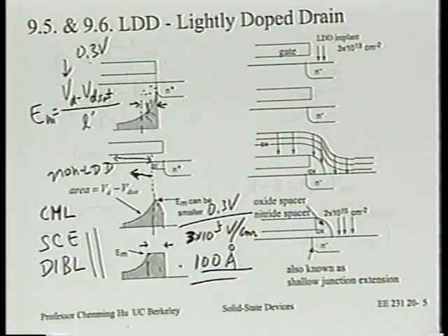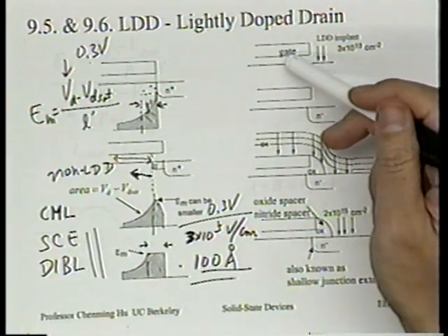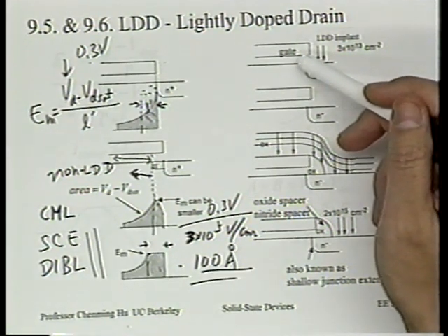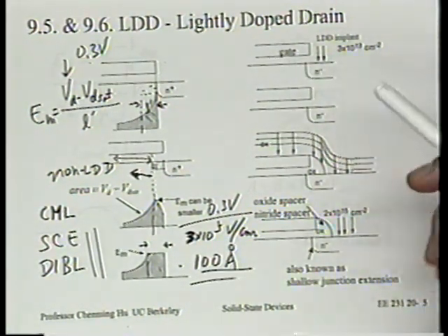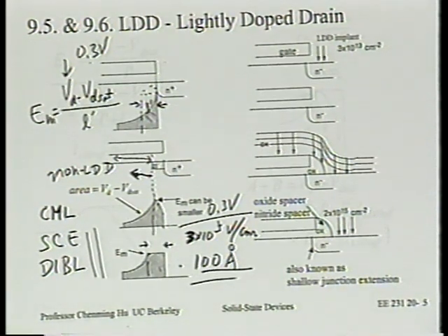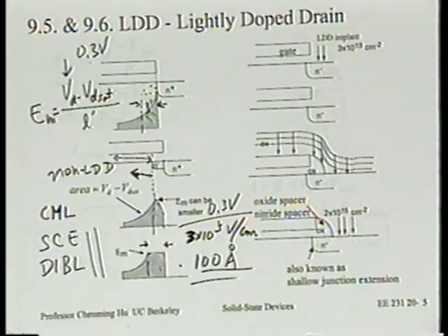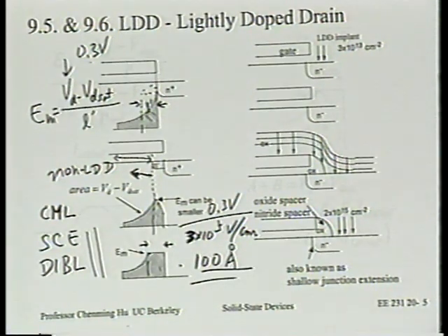In other words, in the quasi-2D equation that you set up, on the right-hand side there's a charge term, right? We assume that charge is independent of y. So you just put in a term that's a function of y, and make the left-hand side, which is the electric field, constant. Now you force the left-hand side, d dy, to be 0. Then you can figure out what the charge as a function of y needs to be in order for the electric field d dy to be 0. That's all. So it certainly can be done.